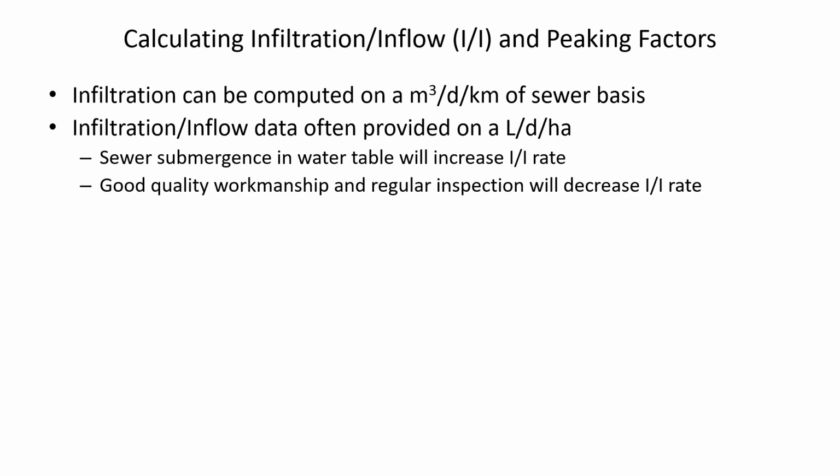Sometimes it's just based on the area that's being drained rather than based on the length of the sewer. And there's a lot of regional variation in how much infiltration and inflow. Like when the sewer pipe is being put in, if inspectors who are evaluating the contractor's work are really careful to make sure that the trench is bedded correctly, that it's on a good slope, and that there's a nice flat gravel bed underneath the pipe, then the pipe, which is generally made out of concrete, sewer pipes are, it's less likely to crack if the base of the trench is laid out with a lot of care.